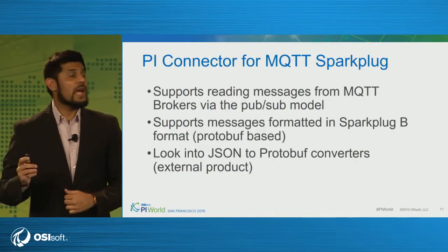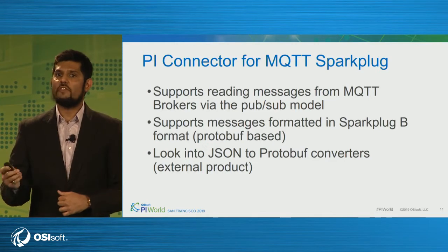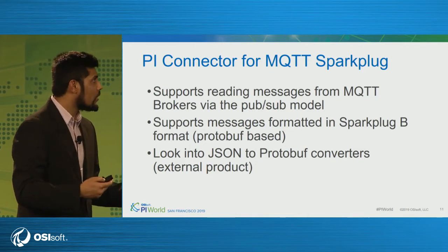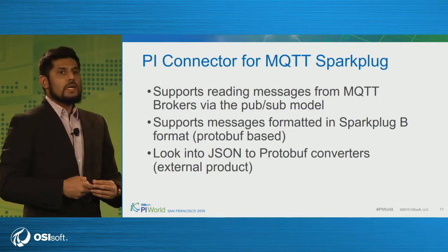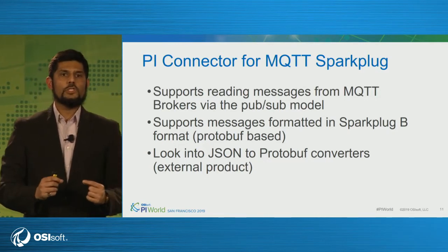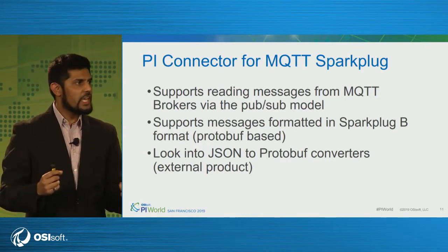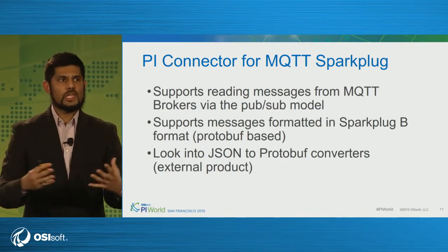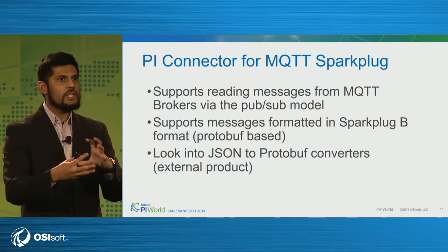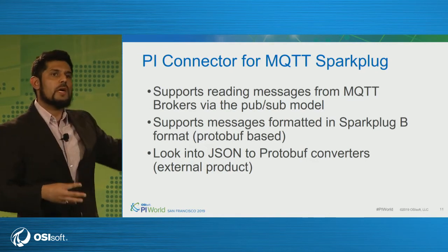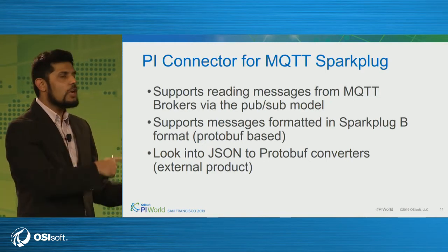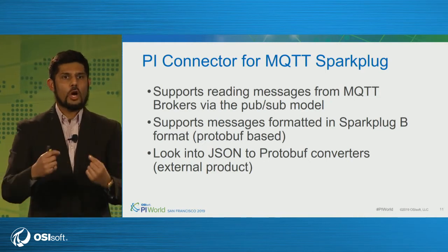And last but not the least, Pi connector for MQTT Sparkplug. This is a very popular one. I've had a lot of people come up to me, talk to me. I've had emails around this connector. One thing to clarify in regards to this connector is this connector supports only the Sparkplug B specification, which means that for anyone who's worked with MQTT, MQTT is a transport protocol, just like HTTP. The payload definition is done using the Sparkplug B format. So if you are sending a payload with MQTT which does not match the Sparkplug B format, the connector will not be able to understand it.